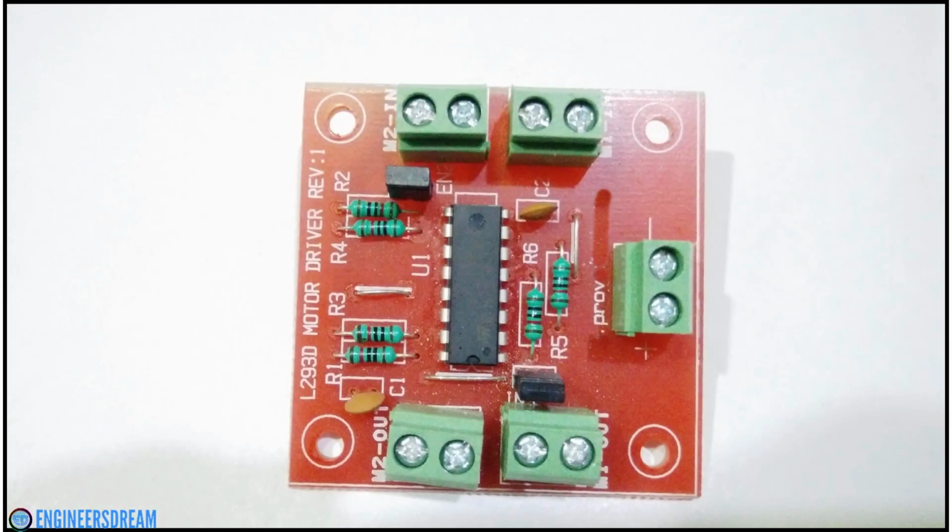Now, if we look at the second motor driver over here, then it consists of 5 green sockets. The input pins of the L293D IC are connected to the top green sockets which are labeled as M1 in and M2 in. So, at M1 in and M2 in, I had to connect the inputs from the Arduino. The output pins of the motor driver are connected to the bottom green sockets over here, which are labeled as M1 out and M2 out. So, to these sockets, I have to connect the DC motors. You can also see that there is one more green socket on the right side, and to this green socket, I had to give external power using a battery.